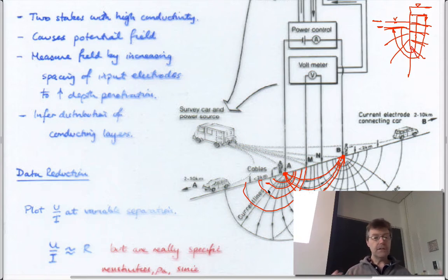So in the same way that electricity is a potential flow, say you put 100 volts across this by a battery between these 2 points. It would make electrons flow along these paths. And if this was 100 volts here, this is 0 volts here. I don't know how many of these there are. 1, 2, 3, 4, 5, 6, 7, 8, 9, 10, 11, 12. Let's make this 120 volts. Then this would be 110, 100, 90, 80, 70.